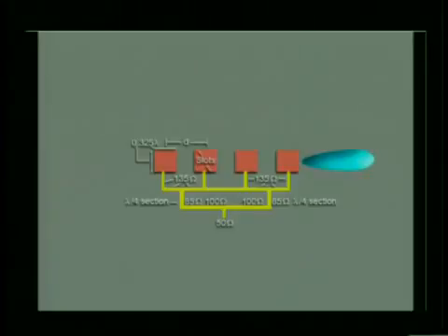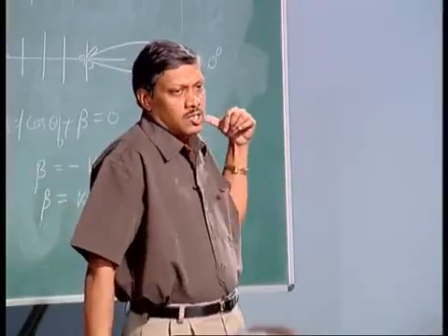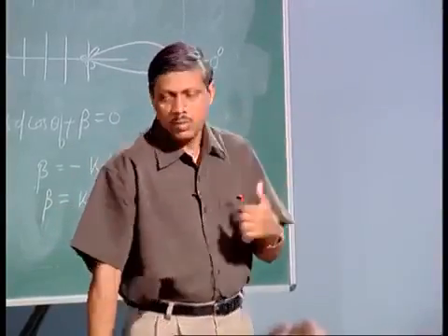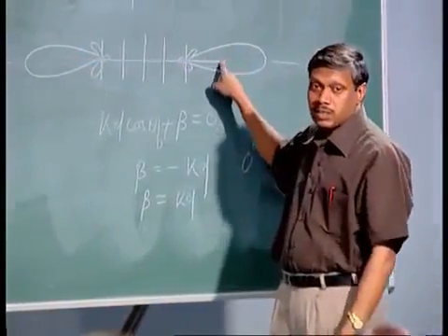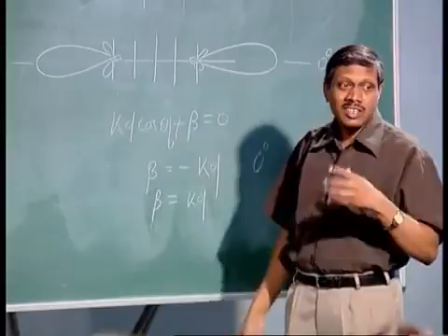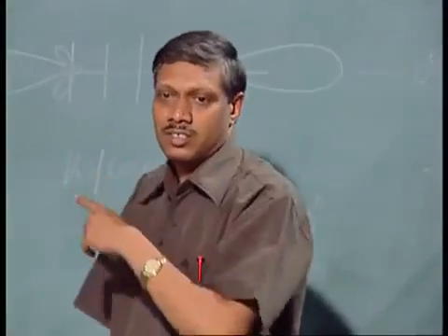And this is to show you how the end fire will radiate. You can just have a look. You have radiation in the 0 degree direction with certain minor lobes accompanying the main lobe. And similarly, you have radiation in the 180 degree direction. As I have already told you, in the 0 degree or 180 degree you may get maximum field, but this ordinary end fire array does not guarantee that maximum directivity will be in that direction.